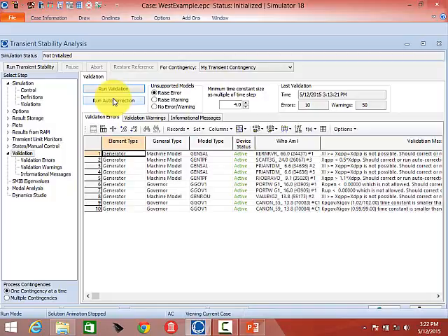And I will say in PowerWorld, when you run auto-correction, it does change the value. We could have set it so that the value stays the same on the power flow side and just what's shipped over to transient stability is changed. Maybe PSLF is doing that, I don't know. But we changed the value. So once it's changed, it's changed.